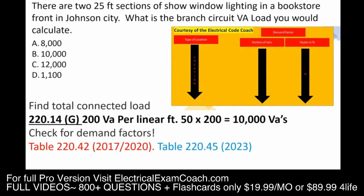We're going to head over to that same table and we're going to look for our type of occupancy here on the left. And we're not going to find it. We're going to find that we cross over and that it's 100%. So there's no demand factor applied. And we're going to select B. Great job.